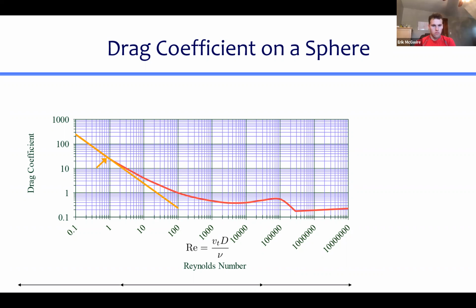There was another graph where there was a linear region where it was laminar, and then there was this crazy... Yeah, somebody's talking now. Is it the Moody diagram? It is the Moody diagram. So yes, it's describing exactly the same thing as flow through a pipe. It's just that this time it's flow around the sphere.